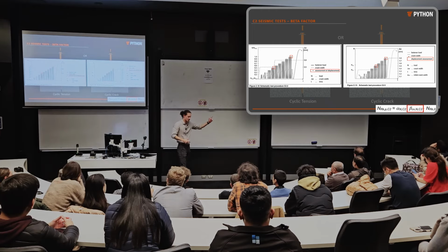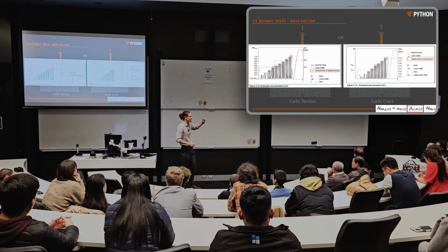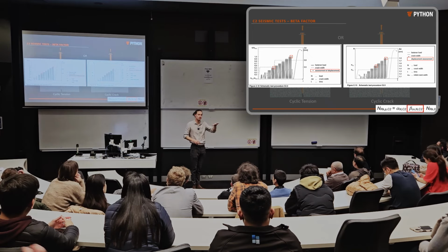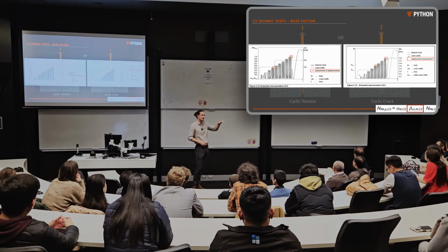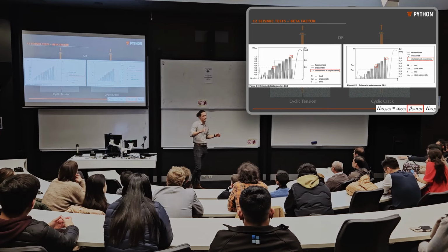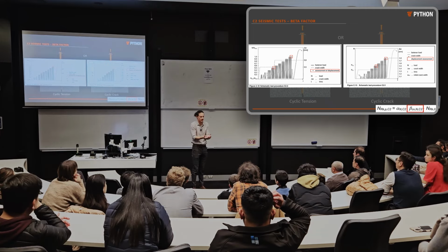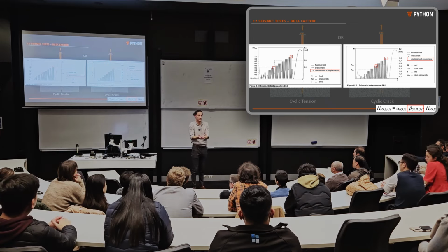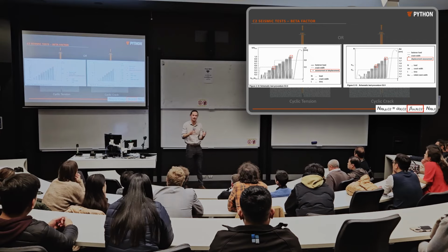Now, in my experience, the actual impact of this on your end result is relatively small, but it does have limits built into the calculation. What this does is it limits the absolute displacement of your anchors at service and extreme conditions, and it limits the spread of displacements. This is so that any anchor with a C2 capacity associated with it isn't going to have excessive displacements in the application that you're using it in. That's the intent behind this. Both excessive displacements or displacements that are hard to predict and variable. That's the two things that it's protecting against.